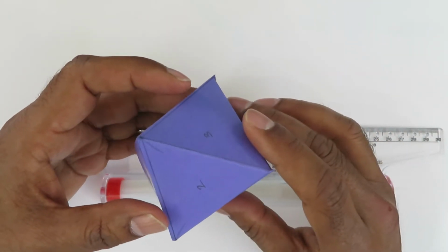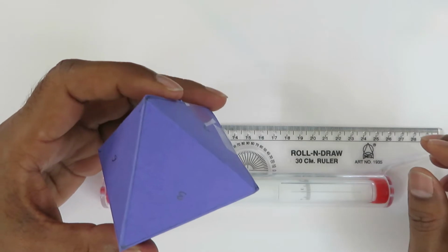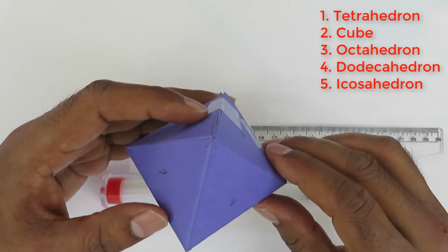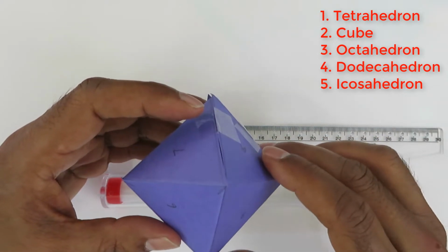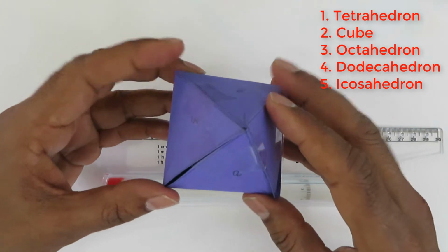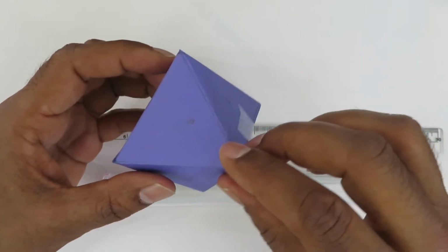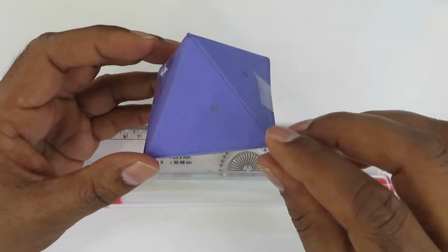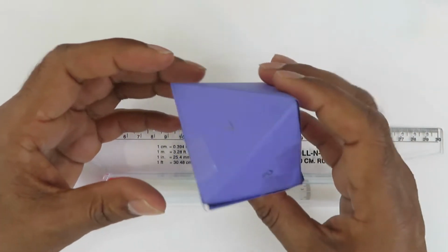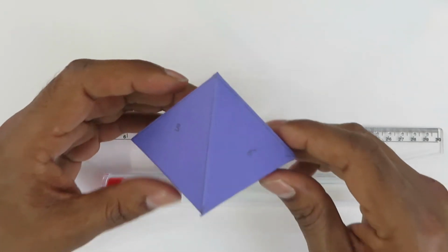So this is an example of what is known as platonic solids. There are 5 types of platonic solids: tetrahedron, cube, octahedron, dodecahedron and icosahedron. Octahedron is one of them. Here you can see that all the axes are the same in length. The faces meet at the vertices and make the same angle. So this vertex is the same as this vertex. So this shape is completely symmetric. So this is the shape, and we are going to draw orthographic projections of this shape.